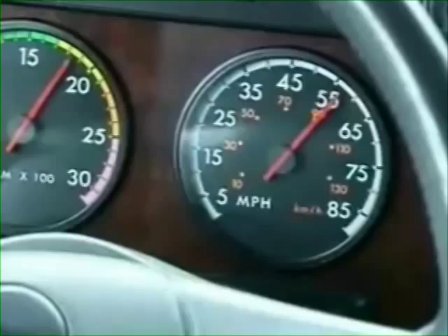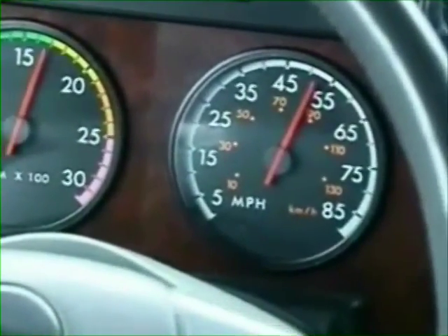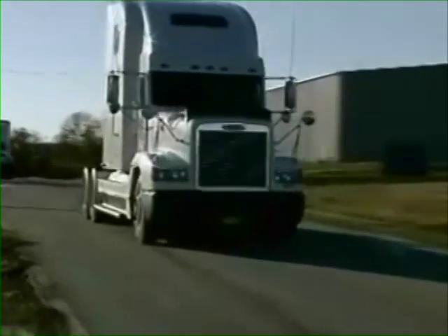Vibrations which are experienced between 50 to 60 miles per hour, but not above or below that speed, are generally related to tire wheel runout. Vibrations that worsen with increasing speed are usually the result of an out-of-balance situation on a rotating component.